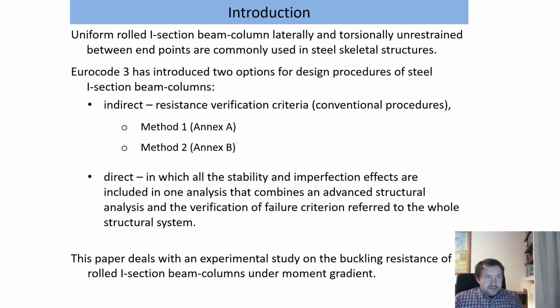And the second, the direct method, in which all the stability and imperfection effects are included in one analysis that combines an advanced structural analysis and the verification of failure criterion referred to the whole structural system.